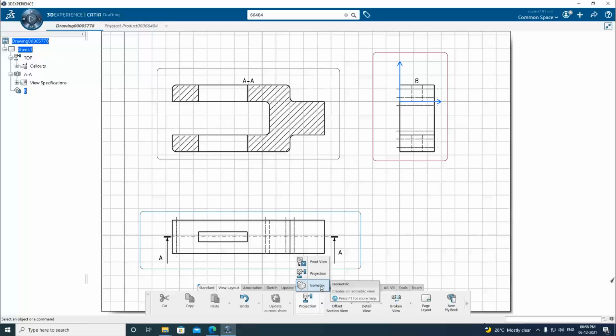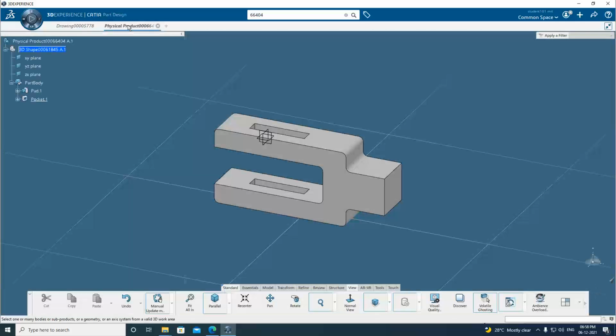Now in engineering graphics, I'm very sure engineering graphics 1 you have done the isometric, engineering graphics 2 you have done the isometric projection. Let us see how to do that. Click on isometric project, that option. It is saying select a reference plane on a 3D geometry. Go to the geometry.